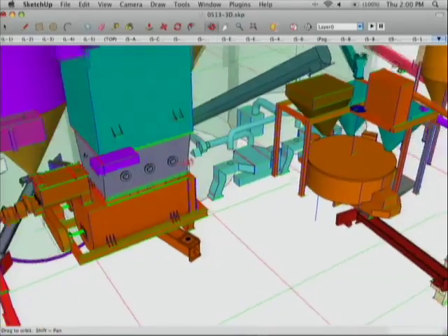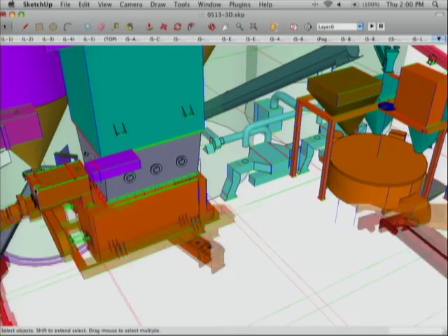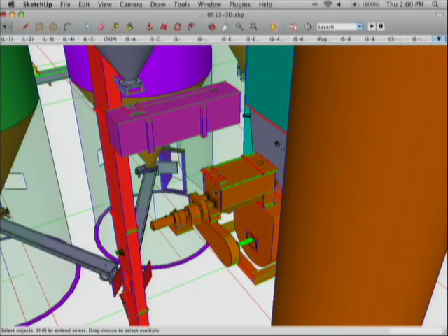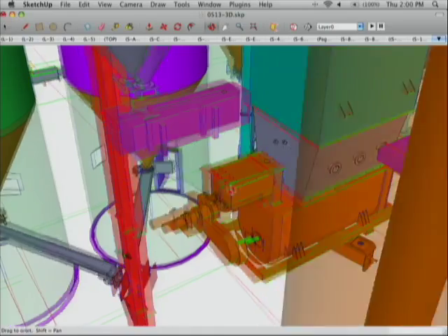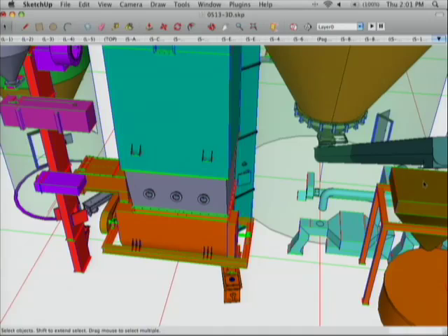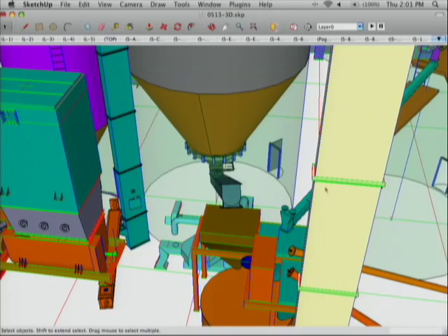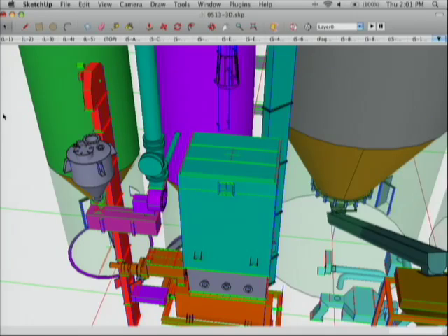So I'm here, I'm rotating somewhere about that point. So if I come over here and double click this, it'll start going about that point. I'll try to do something off. The mighty mouse, unfortunately, the wheel tends to move when you double click the middle button. See, it moved the display all over. So it moved it over to that point right there, which is what I was trying to point at. I'll try to go to this point now. Double click the center button.